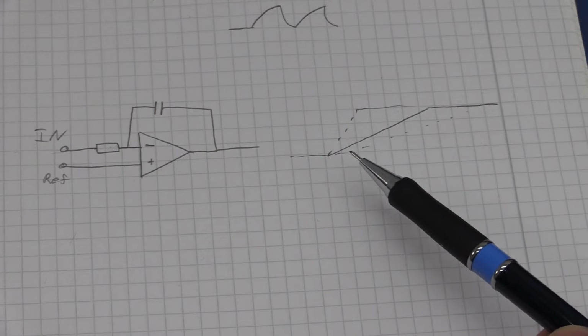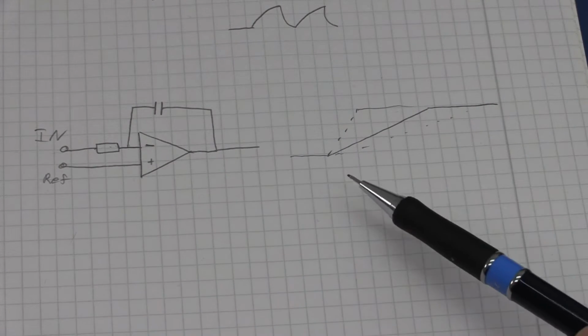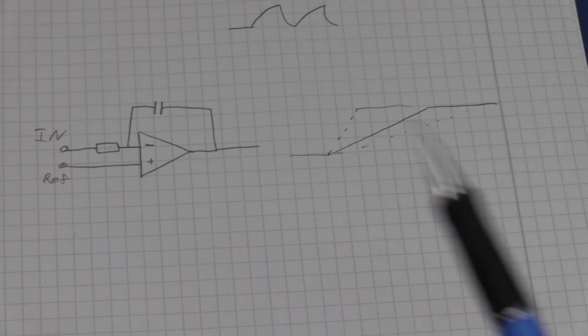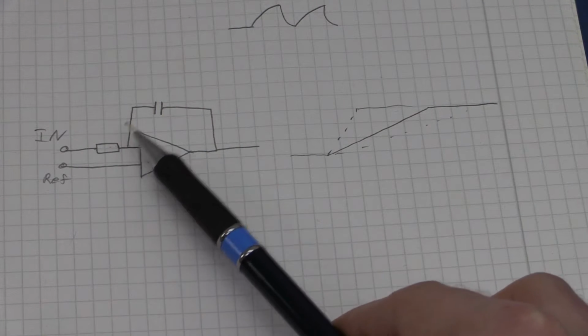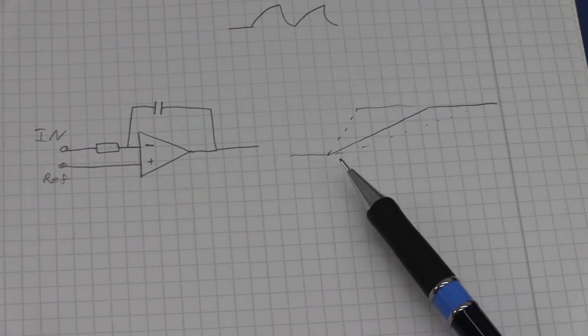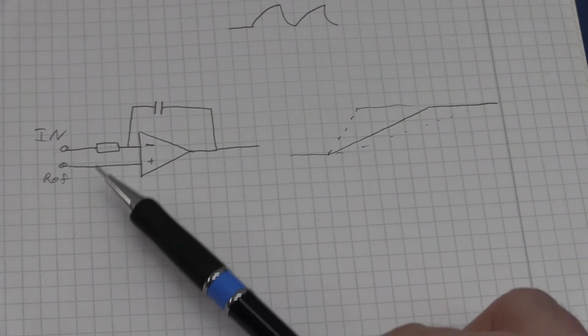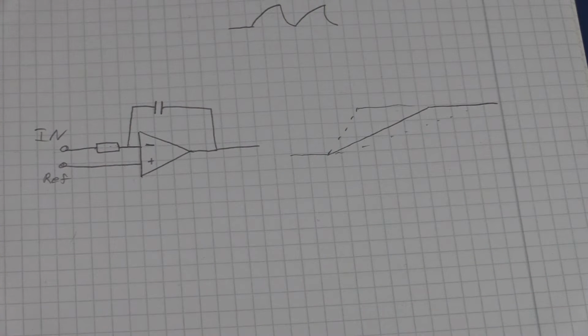A little bit higher we will have a slow ramp, much higher we will have a very quick ramp. And you set this resistor capacitor time constant to give you the slope that you want at a given difference in the voltage.